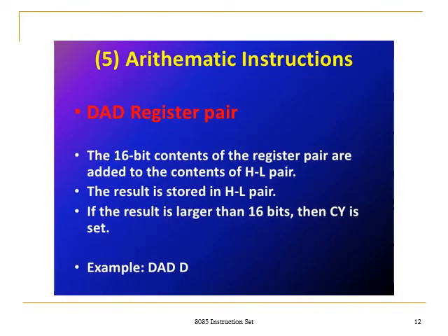The next arithmetic instruction we are going to see is DAD, right? DAD register pair. The 16-bit content of the register pair is added with the HL pair. Here, in the addition operations ADD, ADC, ADI, we did 8-bit addition. If you want to perform 16-bit addition, a provision is there, an instruction called DAD. This DAD directly adds the 16-bit values in the register pair.